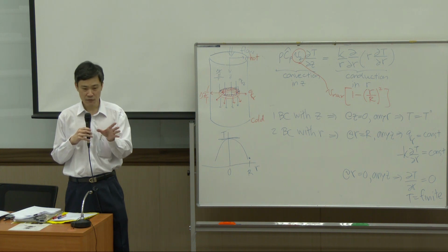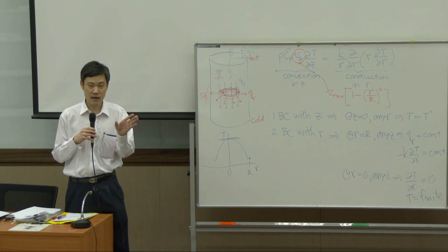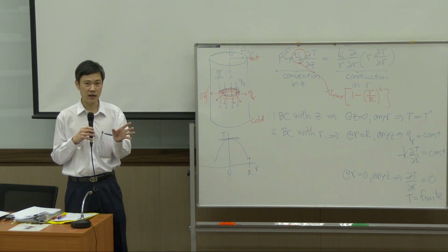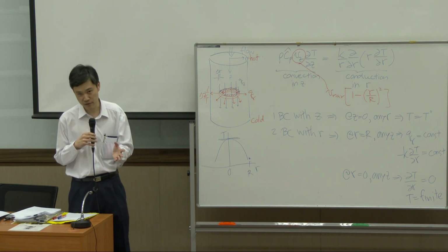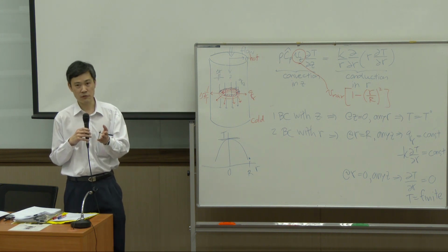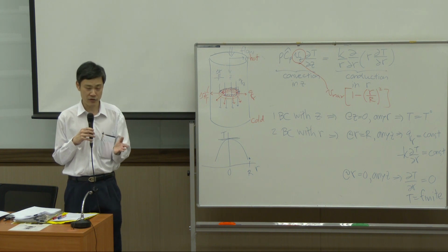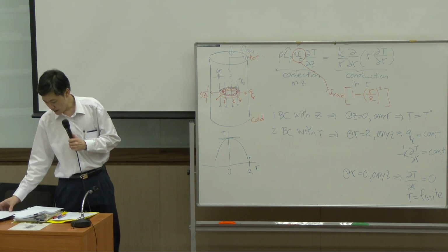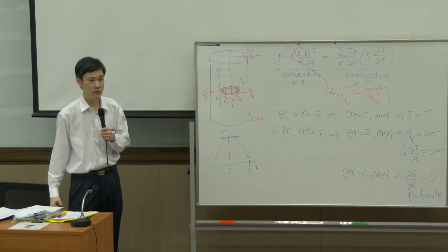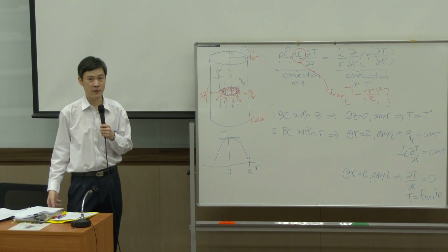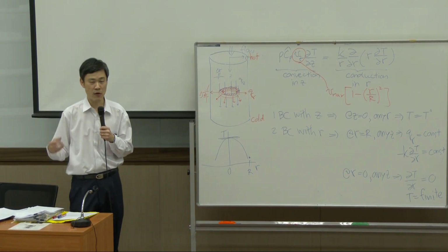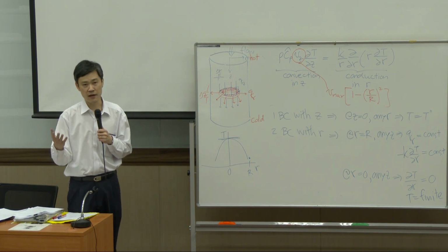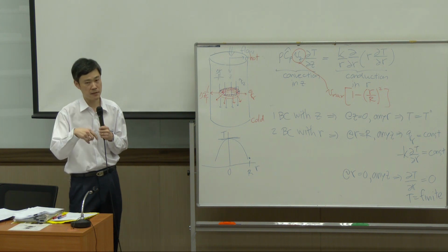But in that case, we also incorporate convection, but convert the form of convection using Newton's law of cooling so that convection can be represented by using the conduction equation. So the first and second examples rely on equations based on conduction. The third example is basically the flow in a slit with viscous heat. That example shows how important the viscous heat of flow work can be. If the flow work is high enough, you can have an increase in temperature within the system.